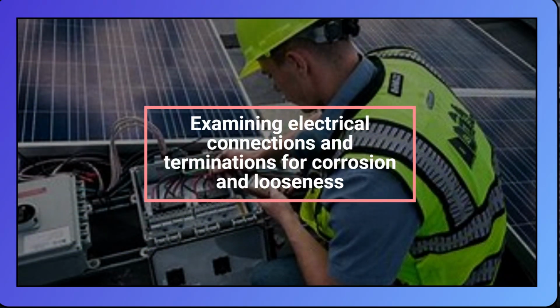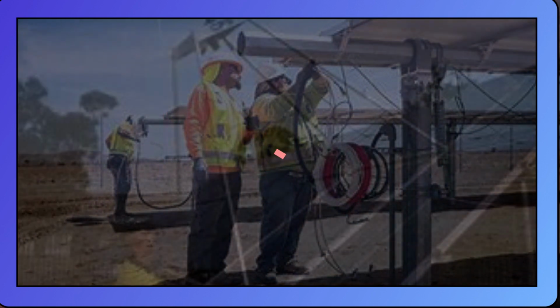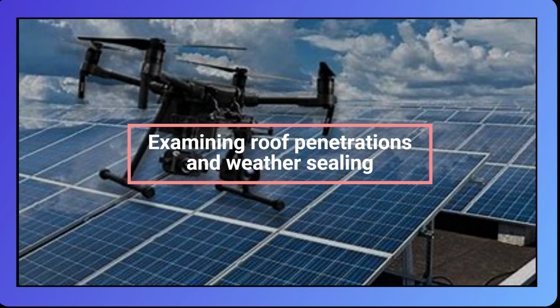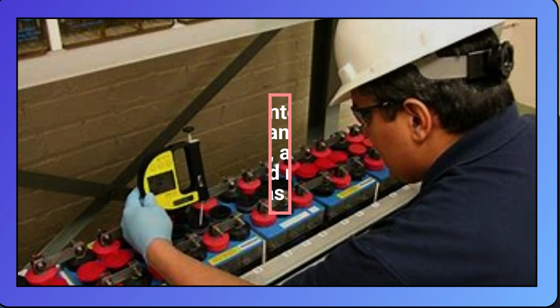Examining electrical connections and terminations for corrosion and looseness. Verifying that wiring harnesses are securely coiled and packaged by looking at them. Verifying the PV array's cleanliness, damage-free status, and structural soundness. Examining roof penetrations and weather sealing. Battery maintenance may involve cleaning, adding electrolytes, adjusting the charge, and replacing the batteries as necessary.